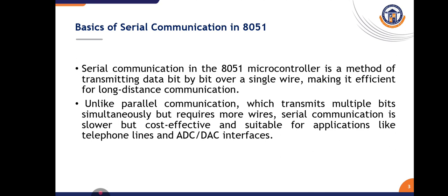In the case of the 8051 microcontroller, the communication involves transfer of 8 bits using a data bus, so it needs to be 8 bits wide. Parallel communication is definitely fast but requires more connections. This leads to higher cost and hardware complexity compared to serial communication. So that is why we go for serial communication.